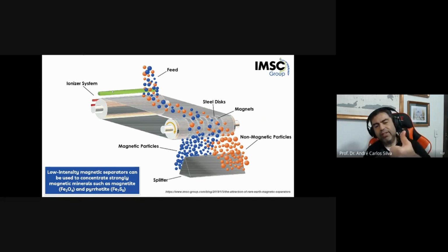So we have ore sorting, now magnetic separation, and even electrostatic separation, you can use this kind of belt. But for electrostatic separation, we'll come back in a few minutes, we use it more for recycling. Recycling has eddy current separators and they are amazing, but not so much for mineral processing. Maybe in the future we're going to have advances in order to tackle this material also. But for recycling, it's perfect. So guys, what is going to happen is if I put my material on top of this belt, the belt is moving, so automatically my material has movement on it.